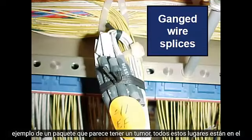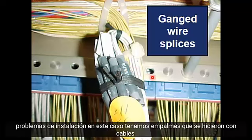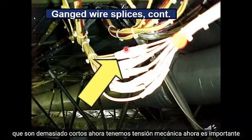Now here's an example of a bundle that looks like it has a tumor. All these splices are in the same place, so now the wire is bulging and it could cause potential installation problems. In this case, we have splices that were made with wires that are too short. Now we have mechanical strain.